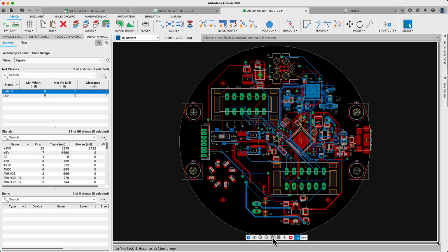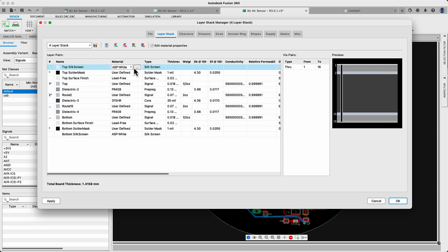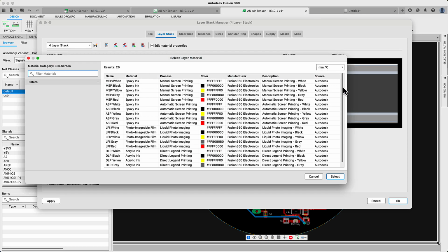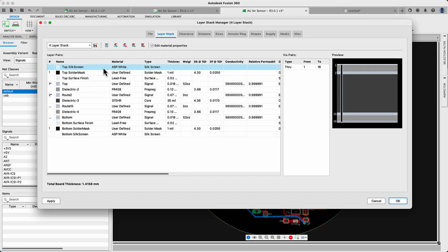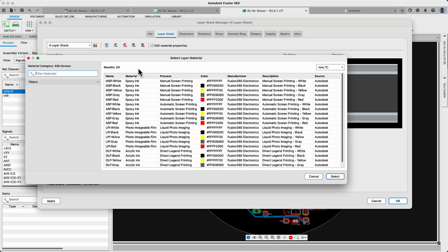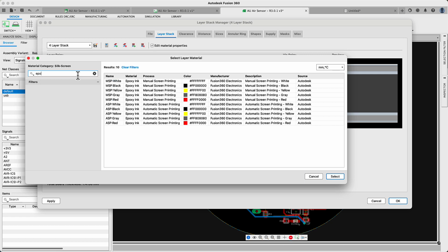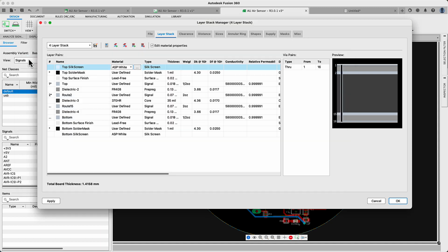We're going to continue working on the PCB Workspace. You may remember that in earlier releases, we added a brand new layer stackup manager, which empowers you to assign specific properties to your layers, such as dielectric properties, thickness, width, and many more. Assigning these properties within your PCB composition allows you to get more accurate results when simulating your board, for instance. For this update, you're going to notice that we have added layer stackup properties for your silkscreen layers.